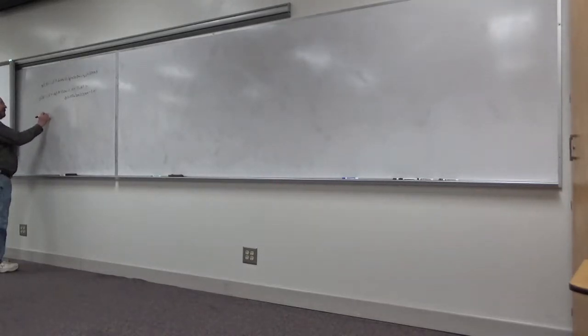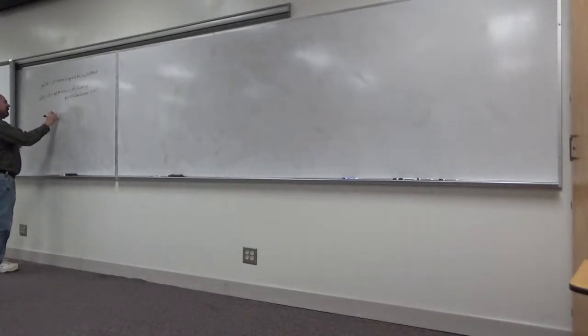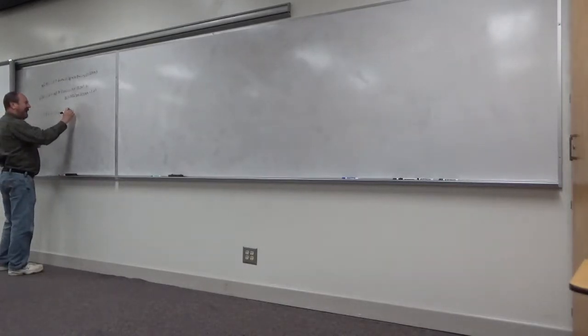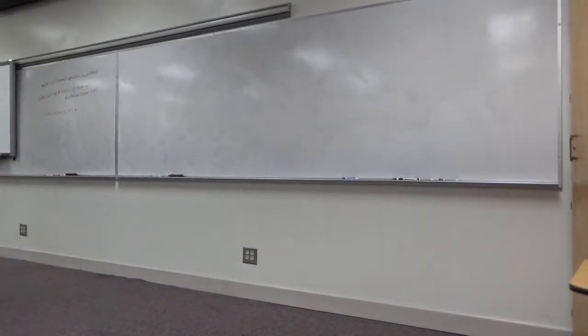Well, I want to go on with the same example because there's something here that's very fundamental. The 1.5 is a DC term, and that has nothing to do with what I'm going to talk about. But I'm going to write this 0.18 times 4, 0.72 cosine of 0.1 pi, and now I'm going to factor that out. 2.05 over 0.1 pi. I've still got MATLAB up here for this one. 2.05 divided by 0.1 times pi, and that is 6.53. n minus 6.53.